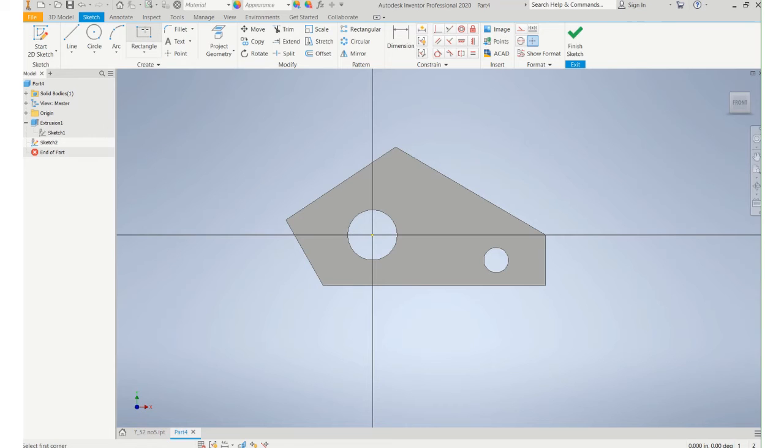I'm just going to stick with the default method, which is going to ask you for 2 corners. Like let's say I wanted to add a foot to the bottom of this. I'm going to click on that intersection. I'm going to click over here. I just want to get to the end of the part. I'm not going to worry about the height of it right now, because then I'll use my dimension tool to call out the height of that. And let's say that's 3/16.